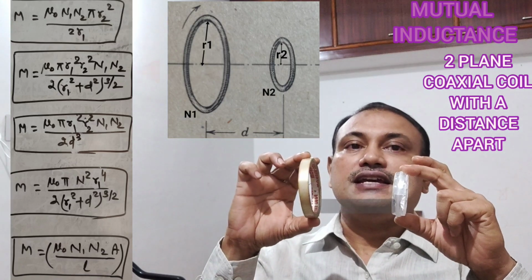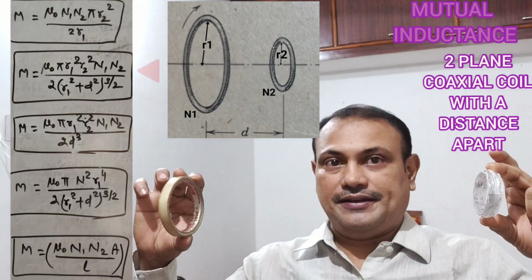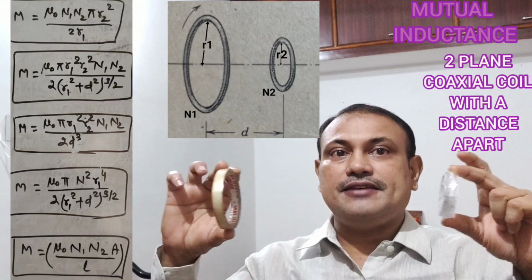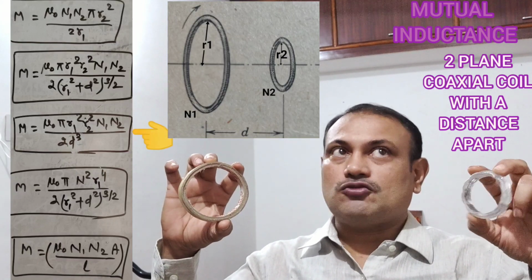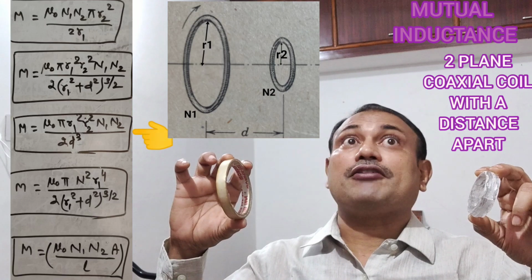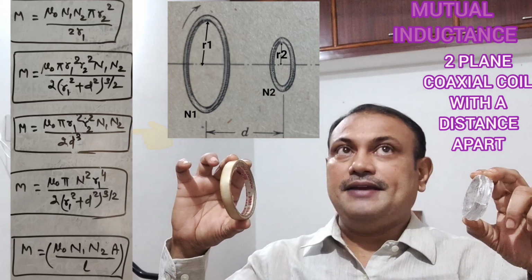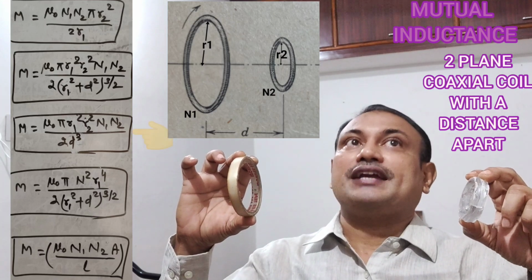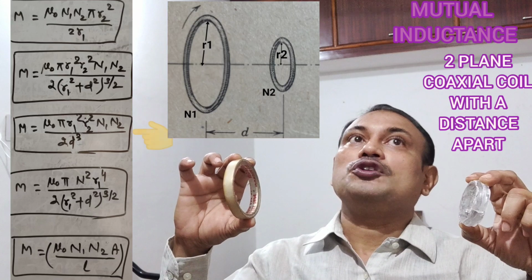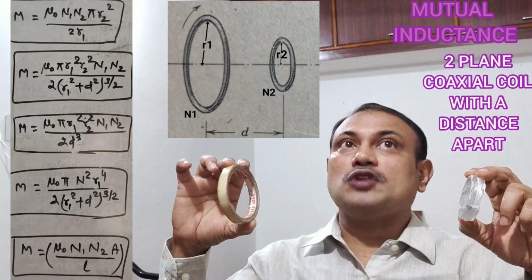And if the distance of separation between these two coils is considerably large, meaning d is much greater than the radius r1 as well as r2, in that case the formula reduces to M is equal to mu 0 times pi r1 square r2 square N1 N2 upon 2 d cube. That is the formula when the separation is too large.